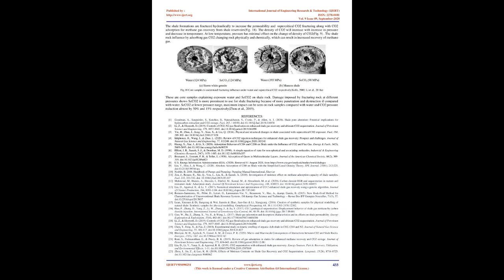The graph, Fig 14 B, represents a change in strain in core samples with increasing time and CO2 pressure. In transient shrinkage, CO2 gets adsorbed on sample cells, increasing pore pressure, and stress is induced gradually. In the slow swelling region, as a lesser number of pores remain for CO2 to get adsorbed, the rate becomes slow, and CO2 gets adsorbed in pores of greater or equivalent size.